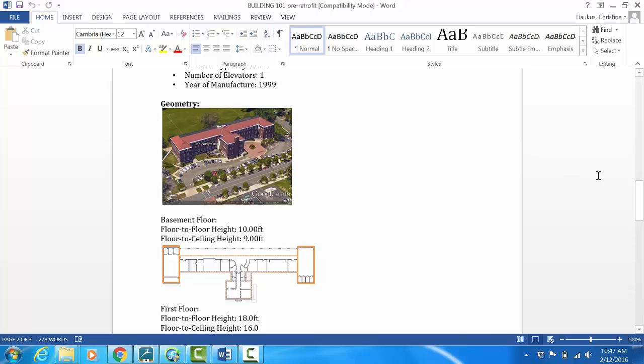We're actually going to break this block down into the first floor and then the second and third floor for the main bar, because the first floor of the bar is a little shallower than the other two floors, which is hard to tell from this picture, but you can see it here in this plan. There's a colonnade in the back, so the conditioned space is narrower. And then this centerpiece and the two ends will be separate blocks. So we'll have 5 blocks total, and I've got dimensions and square footage for these areas.